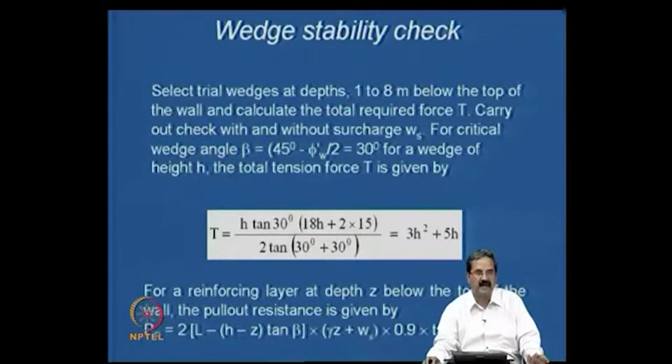But apart from it, as I just mentioned, we need to go for wedge stability checks, which are very important. And as I just mentioned, you need to draw some force polygons and get this tensile force required to close the polygon.